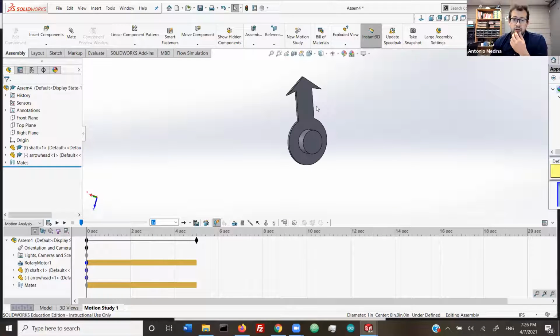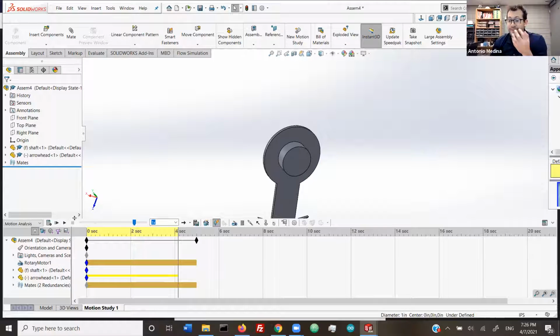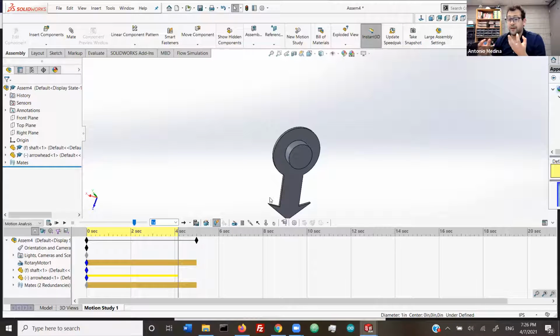So we'll go over here, and we'll hit calculate and it's starting to spin. And it's as easy as, hopefully that's really easy. You just add a motor, start spinning. And you can imagine that as you start to add more complex parts, you can literally within SolidWorks simulate the motion of a servo motor, a robotic system moving its arm up and down. Lots of fun. You can also simulate things moving in real time.